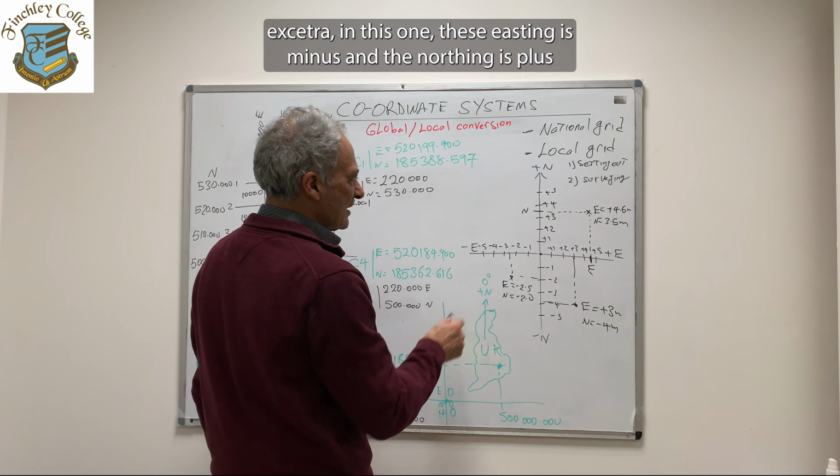Now, in surveying, we never use a negative coordinate. We always have positive coordinates. Therefore, we will avoid using these three quadrants. In our system of surveying, everything will be in quadrant 1, Q1. Quadrant 1, this is where we do all the surveying and setting out.